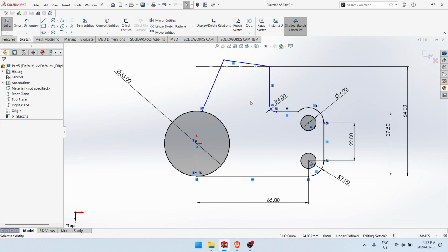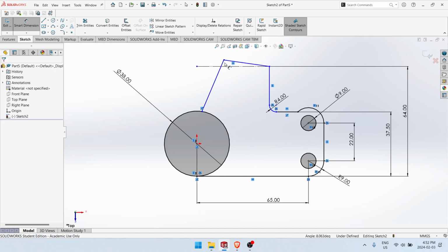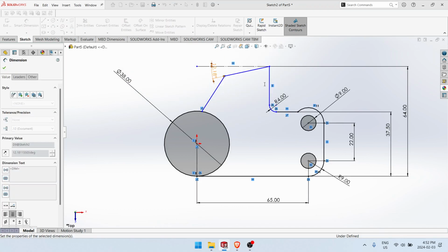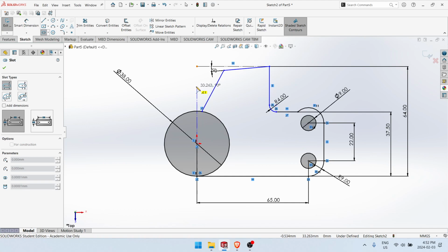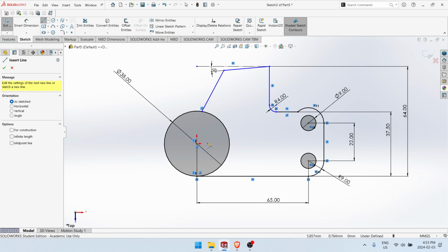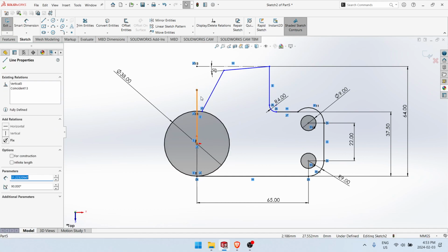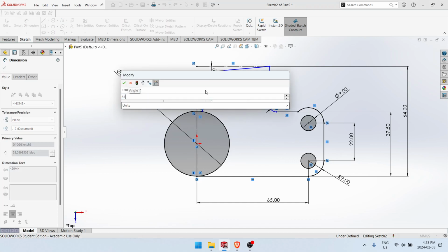In order to measure an angle, you need two lines. So I've created a construction line here. That's 5 degrees, right? I've created a construction line here just so I have a reference line to compare to. You could also do it with any line. You don't need to create these ones specifically, but I'm just doing it how the drawing has it.